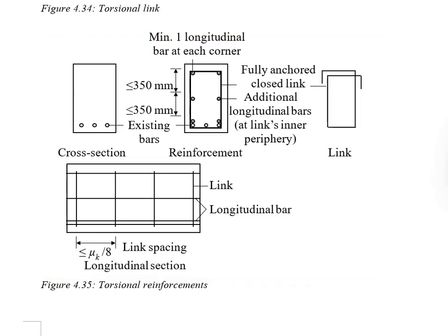The principle is this. By summing up the total reinforcement from what is required in the basic design plus the torsional reinforcement, it is to cater for the most critical situations where both the moment and the torsional loads are at their maximum, or both the shear loads and the torsional loads are at their maximum.